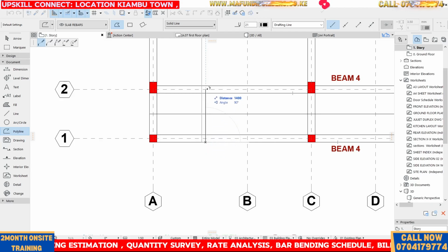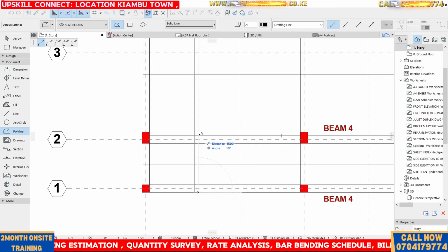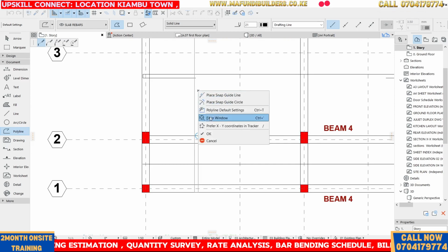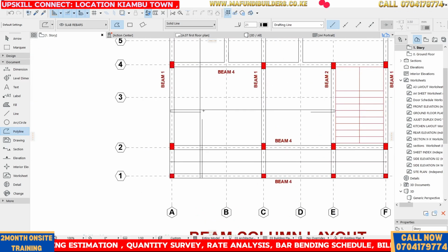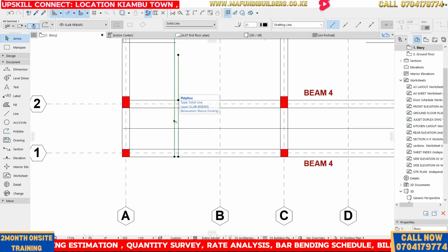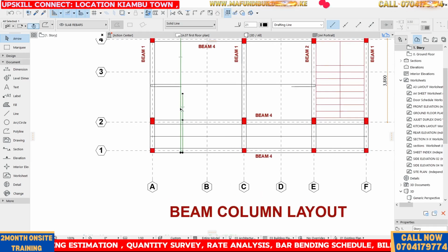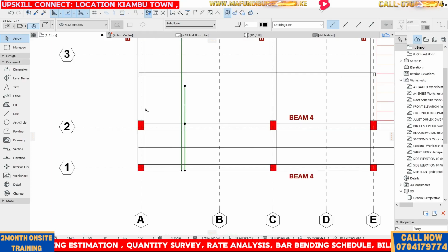100. And then guys, here you can see I'm going beyond the corridor, and then here probably I can do 1200 like that, guys. So the reason why exactly I'm doing this is because now this one will be the top bar. For this one, guys, you need to extend it beyond. You need to extend it because this will be the corridor, and in corridor, guys, you need to ensure that it's well embedded into the adjacent slab, guys.